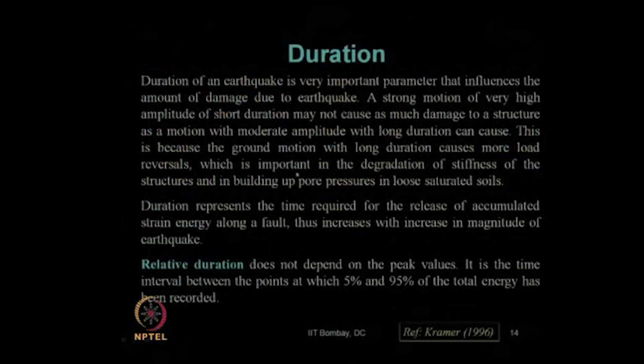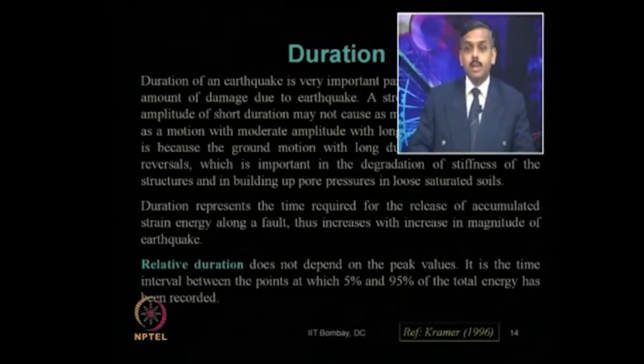This is more important in the degradation of the stiffness. More load reversals will cause more degradation of the stiffness of the structure, and it builds up pore pressure in loose saturated soil. In geotechnical engineering, in case of soil, it builds up the pore pressure. If that favorable condition exists, with a longer duration or more load reversals, it generates more and more pore pressure, which does not get time to dissipate.